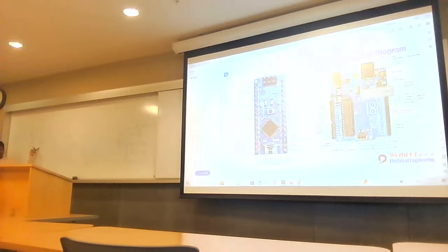And there is a loop filter. The job of this filter is that it produces an error voltage. This is a voltage controlled oscillator. So to maintain 2.8 gigahertz at the output, it produces an error voltage, so that this error voltage can fix the VCO tuning range. You got my point? Let's say if there is any change in frequency here, it adjusts the error voltage so that it can come back again here. So this is the beauty of this closed loop circuit, and there is a frequency divider.